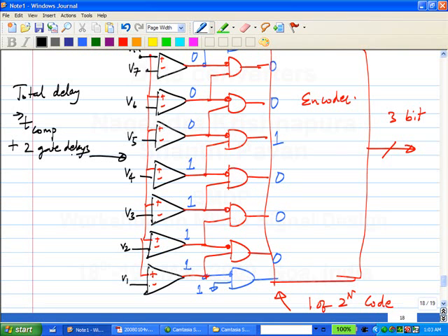That is basically a dumb search. Correct? So finally, A to D conversion is equivalent to searching in which of these 2 to the n bins the input lies. And this is an example of a parallel search, where you have 7 fellows simultaneously looking and telling you if the input is here, the input is there.